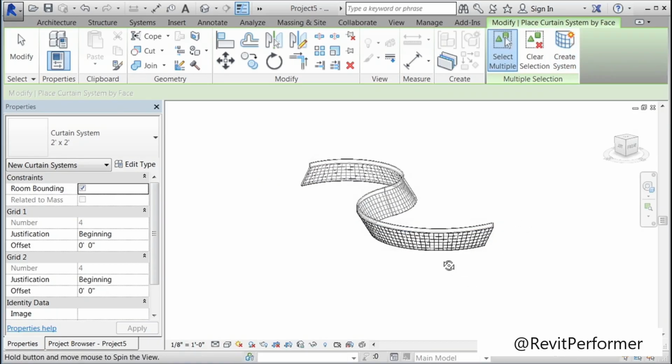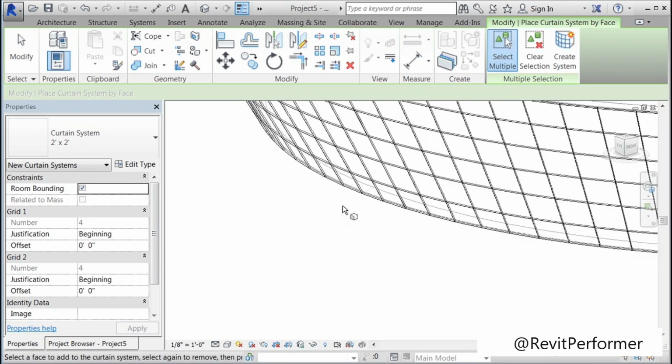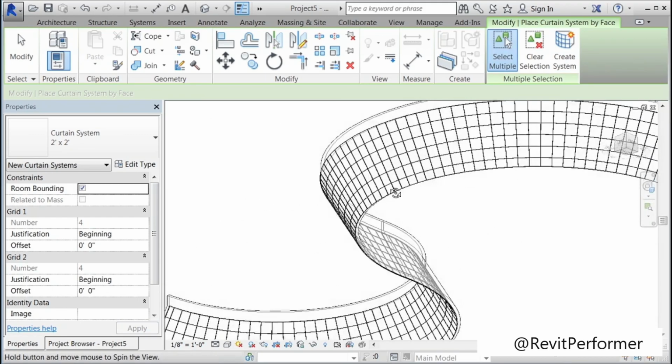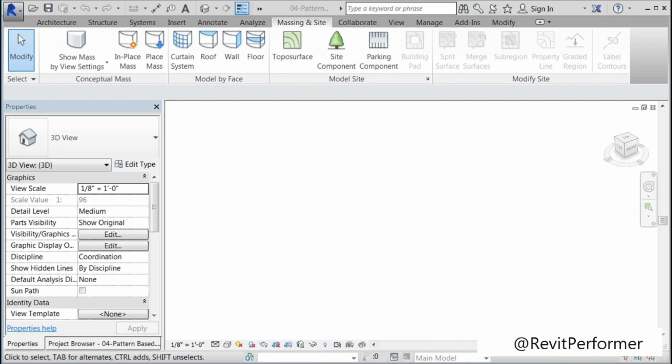Now we have a curtain system that's slanted in section and is radial in profile. Before long, this type of thing is going to become old hat. We will switch our layout to be triangular. We will then add a pyramid-shaped curtain panel, then load it into our model. From there, we're going to apply it to one of the massing walls we already have modeled.